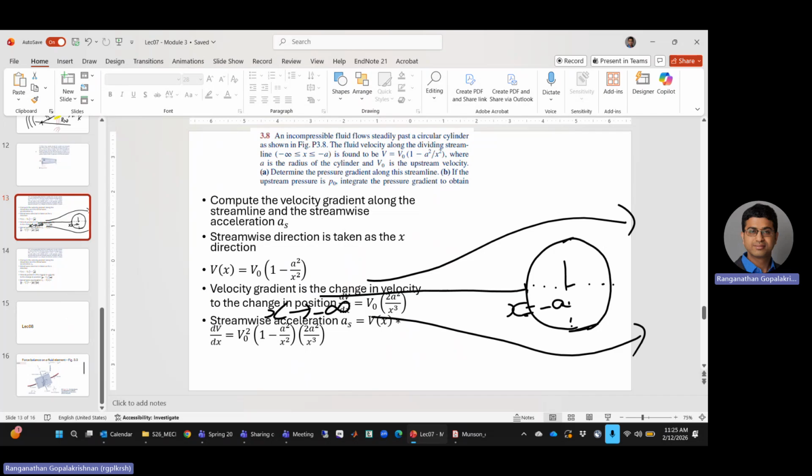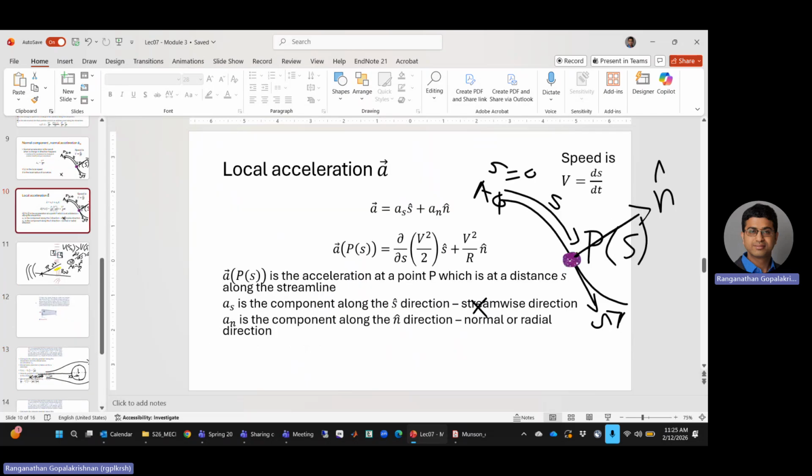Now think of a fluid flow situation where you have a streamline and you take an arbitrary point. This is where the story begins. An arbitrary point, a little parcel or a fluid particle, and we are going to do a force balance on that little particle. Okay, see so far, all right. So that little dot I put here, imagine that is a very teeny tiny amount of fluid with still enough molecules that you can call it a fluid, and we are going to do a force balance on that tiny fluid particle.